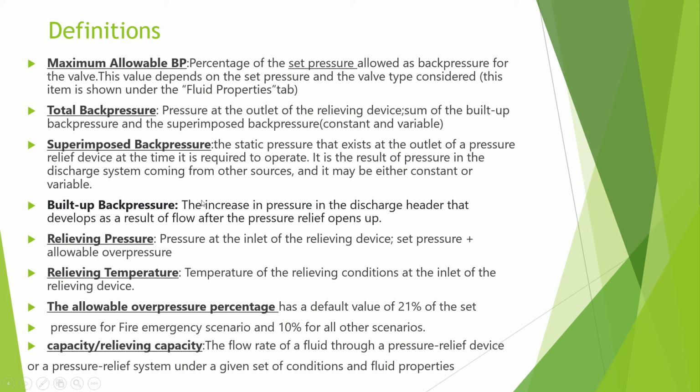Relieving pressure is the pressure at the inlet of the relieving device that is defined as the set pressure plus allowable overpressure. The relieving temperature is defined as the temperature of the relieving conditions at the inlet of the relieving device. Another definition is the allowable overpressure percentage.